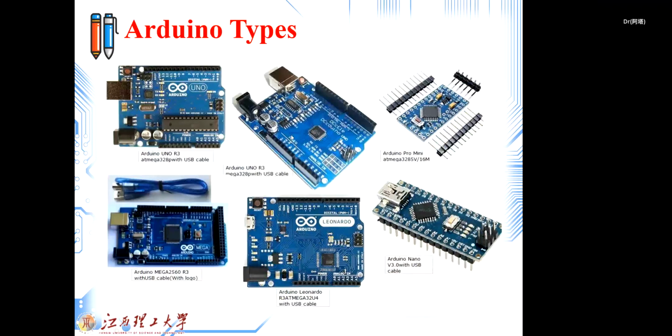From the physical look of Arduino, you will see that the boards are different even in their shapes, but there are also generations of them. The current generation of Arduino is the Arduino Uno R3, which we can have in chip form like DIP mode or SMD part. I personally prefer the DIP mode of the Uno because if the IC is burned, you can change it. But it's very hard to change the SMD part.